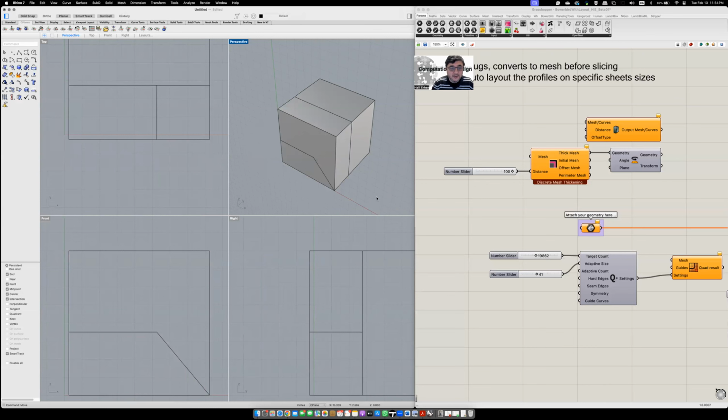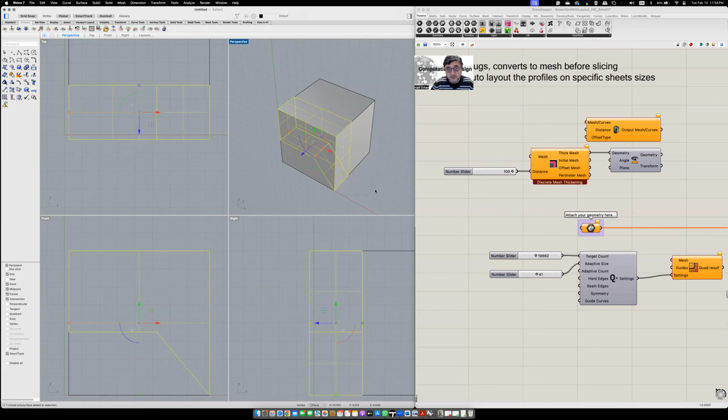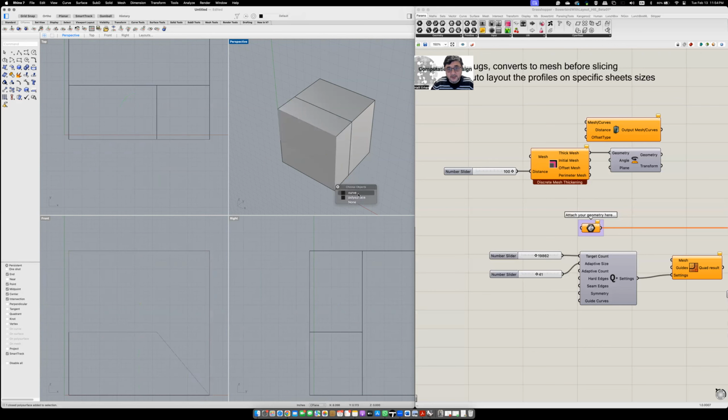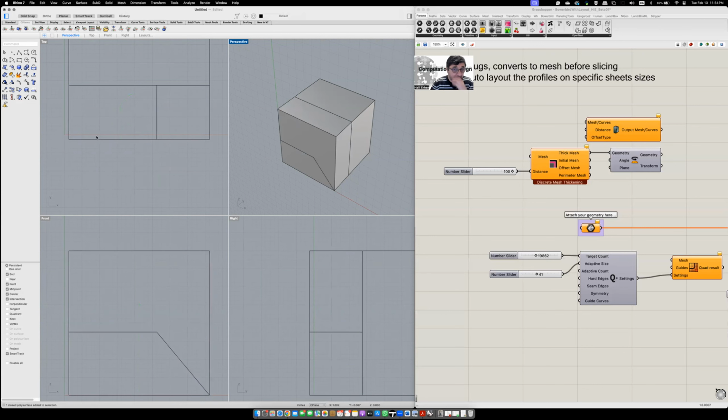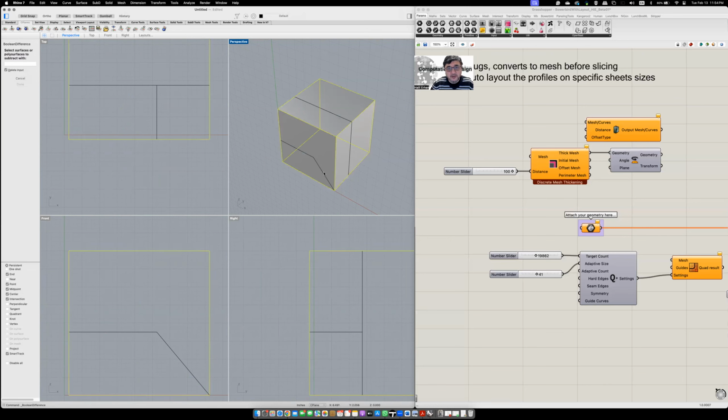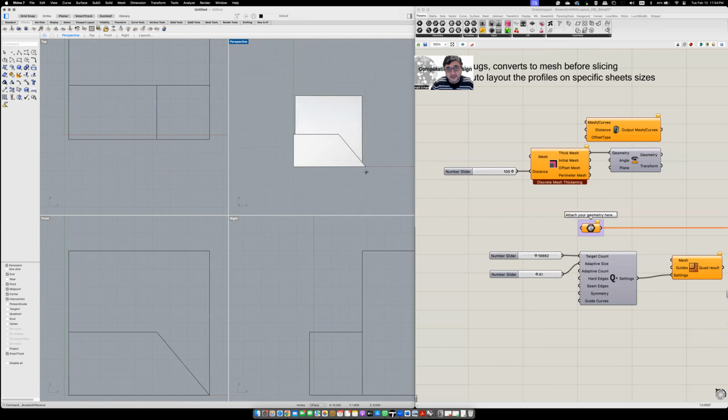Let's position it here. Let's cap our object because this object is not solid yet. So I have 2 solids, right? This poly surface and the other one. Get the curve. I don't need the curve anymore. This is my solid object. This is good, right? So I'm going to use the Boolean operation, the difference, from here. Take this out. So I got this part done.